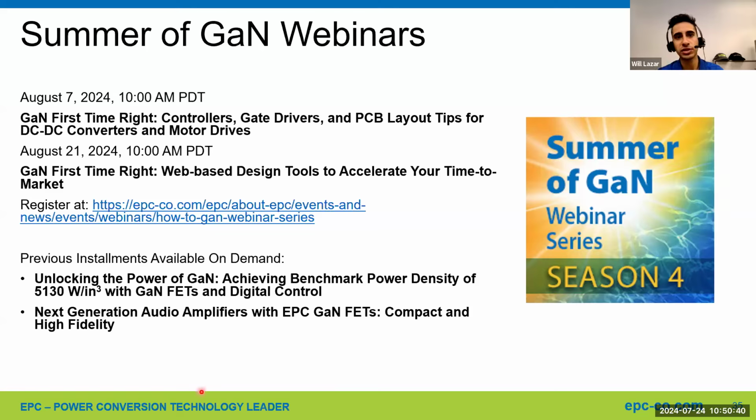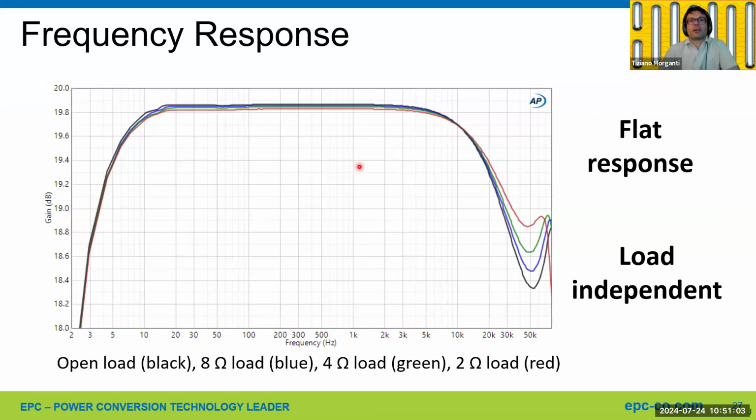Why have you closed the feedback loop after the filter? Okay, that's a good question. One reason to do that is to achieve a better control of the output of the amplifier. I mentioned, I can also bring up the slide, this one. I mentioned I have a very small output impedance up to 20 kilohertz, and this is guaranteeing the least noise coupled to one channel from other switching devices on the system.